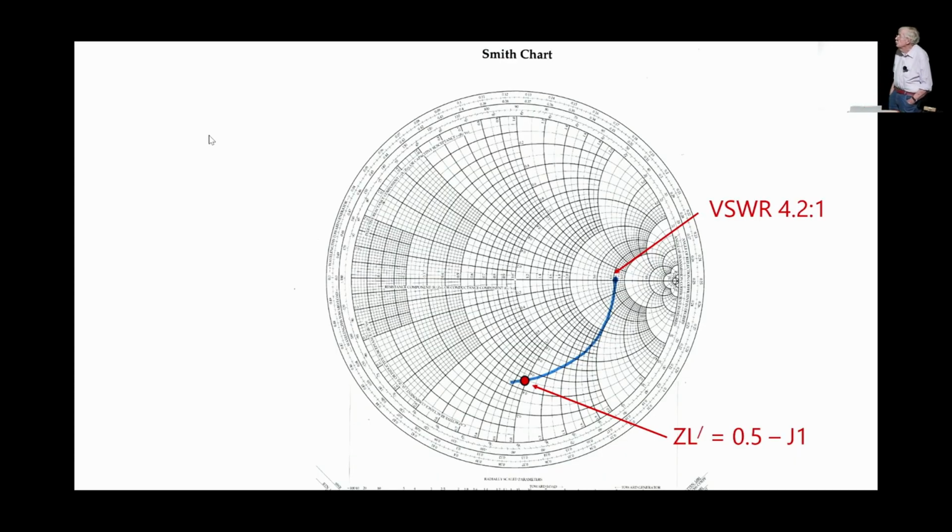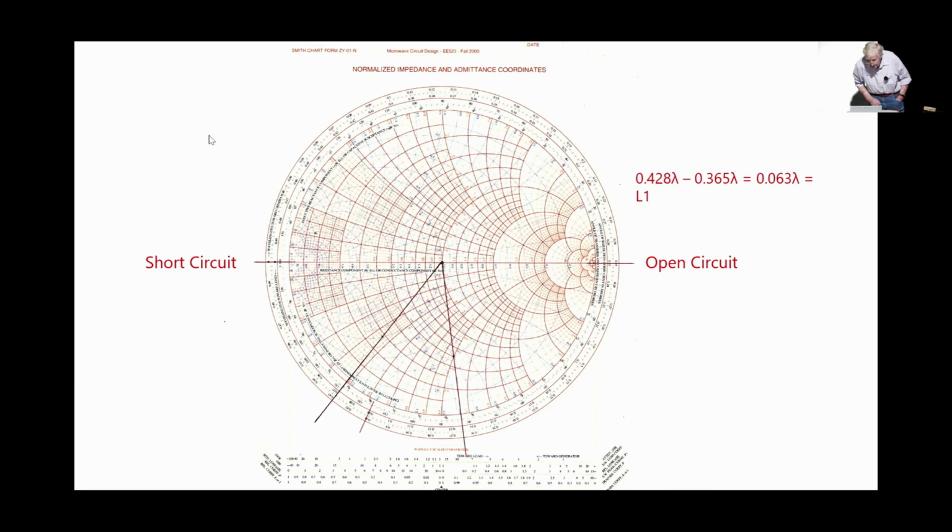There's my impedance normalised, and I just take the circle around to that axis there, and you can actually read off the VSWR that's generated by that impedance on the Smith chart. And there's the plot of that's actually the stub that we need. If I go back one, I'll leave it there.